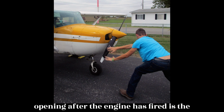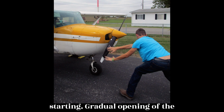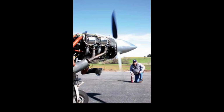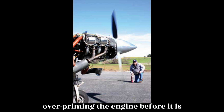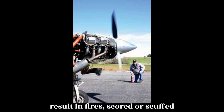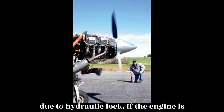Excessive throttle opening after the engine has fired is the principal cause of backfiring during starting. Gradual opening of the throttle, while the engine is cold, reduces the potential for backfiring. Slow, smooth movement of the throttle assures correct engine operation. Avoid over-priming the engine before it is turned over by the starter. This can result in fires, scored or scuffed cylinders and pistons, or engine failures due to hydraulic lock.